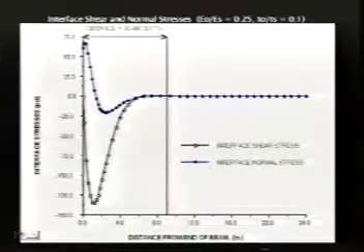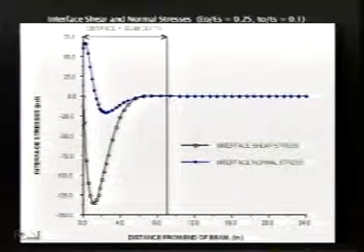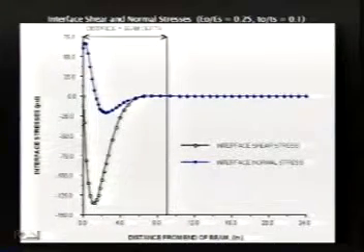They tend to dampen down to 0 by the time you get out about 8 or 9 inches from that edge or that boundary. And I think that's the reason why we always see the delamination beginning right at an edge or the boundary. They normally don't start out in the middle of the overlay unless maybe we have poor surface preparation. But they start right near the edge and they can get to be fairly high.